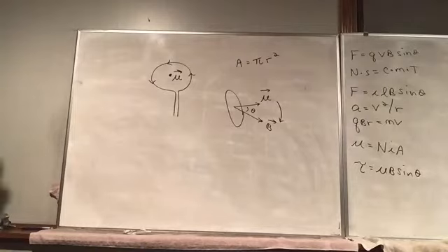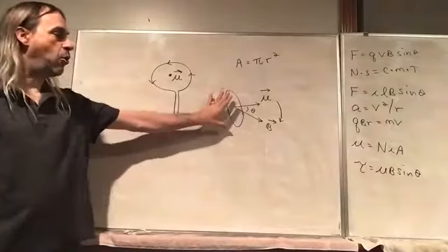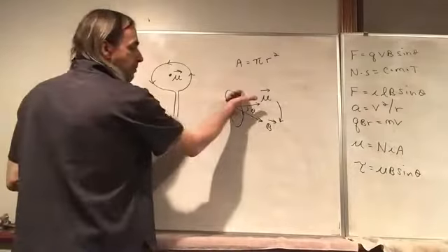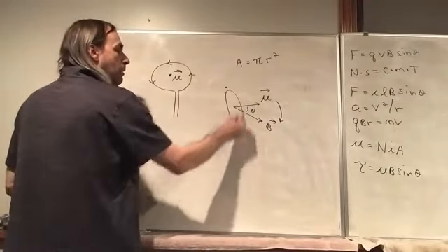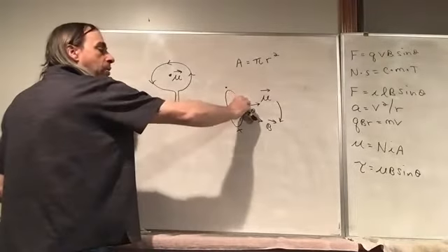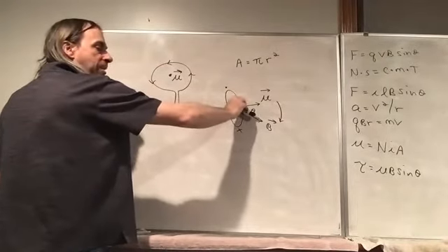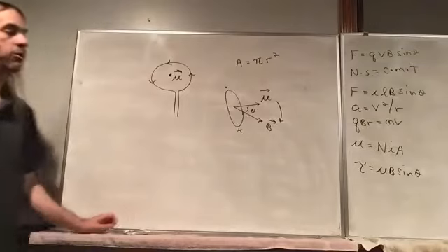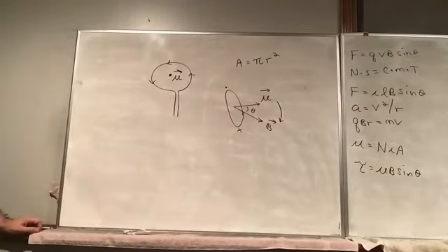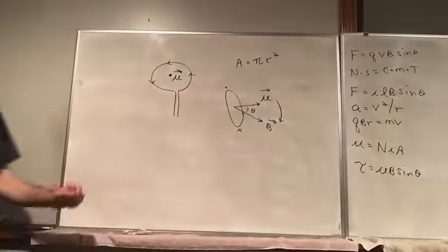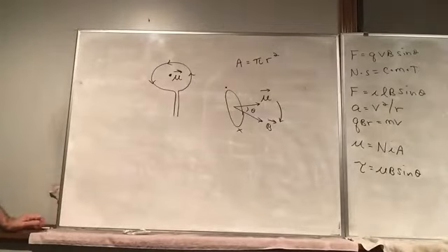We talked about a very simple motor, but if you just have this coil and you have a current running through, it would be coming out of the board here, going into the board there. And so if you just run a coil current through and apply it to a magnetic field, it's going to rotate the coil till they line up, and the torque at that point would be zero, but momentum would carry it past, and now it's going to be slowing down. So the torque is going to be opposing the rotation. So if you release this, it'll just oscillate back and forth for a while before eventually settling in where it lines up with the magnetic field.